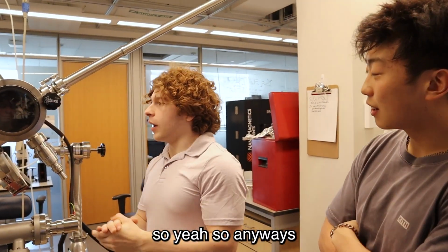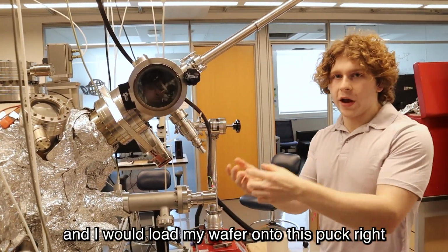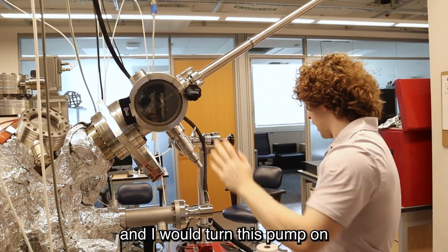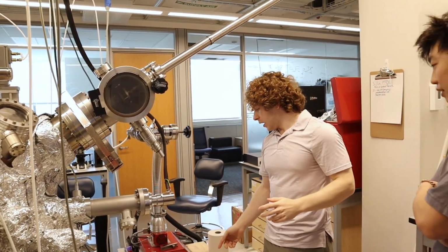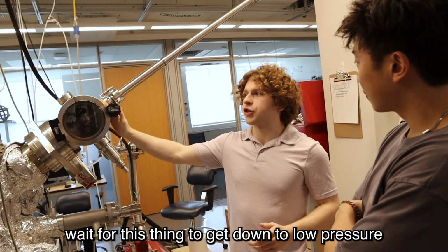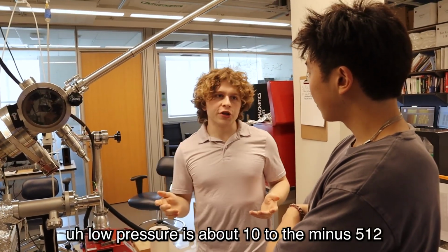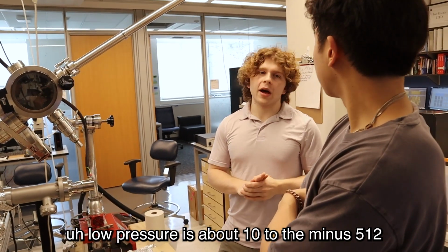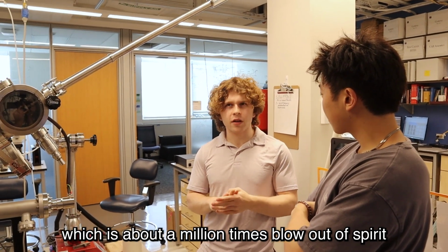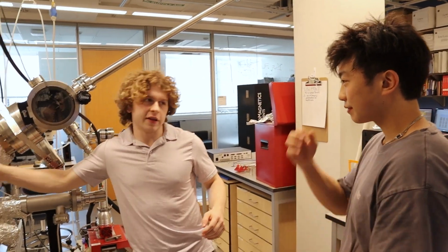So anyways, the first thing I would do is take this puck out and load my wafer onto this puck, right? Then I close this window and turn this pump on. The pump's already on. And I would wait for this thing to get down to low pressure. Low pressure for one of these gate valve areas, which we call a load lock, is about 10 to the minus 5 torr, which is about 10 million below atmospheric pressure, which is really low pressure, but it's not billions, which is what this is.